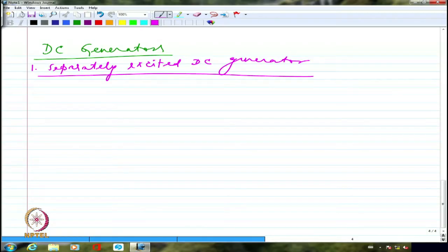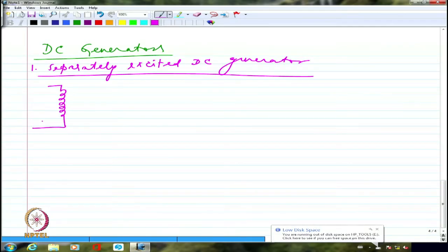Most of the time, in the laboratory as well as in many industries, if I am using a DC generator, which is very rare again, we are going to have invariably the same voltage supply available for armature as well as field. If I am using it as a motor, I might have the same voltage supply, maybe 220 volts or 400 volts. The DC value is fixed. Because of which, the separately excited field will also be in a position to withstand a larger voltage, normally.